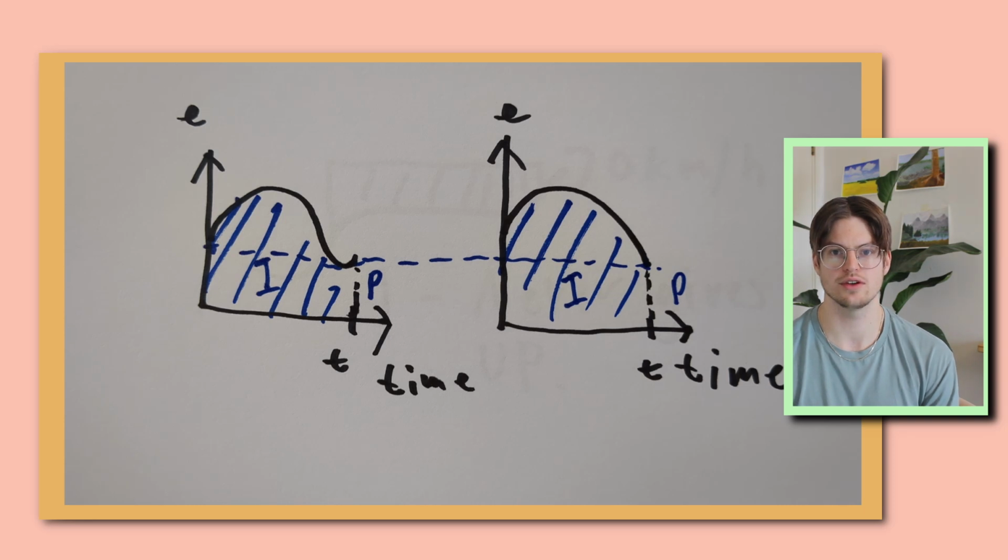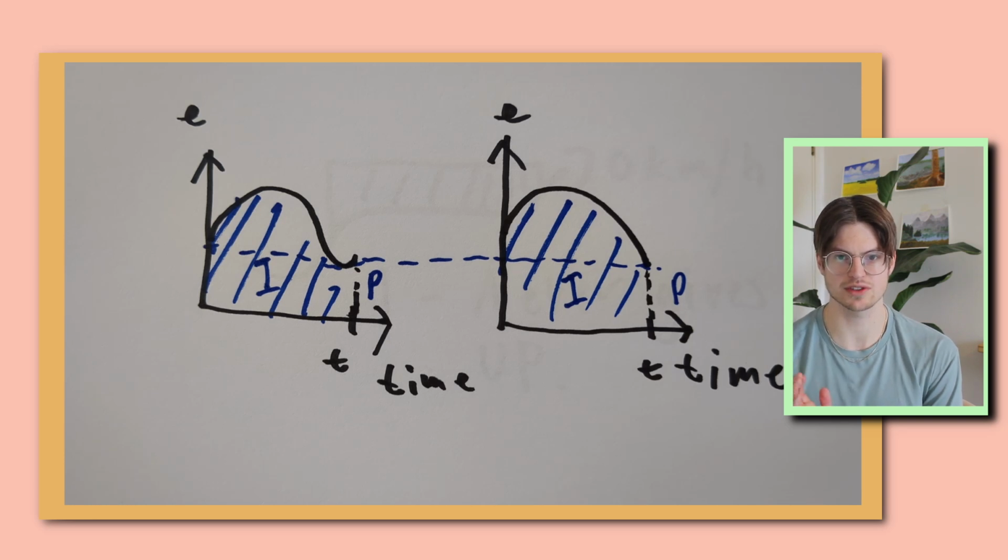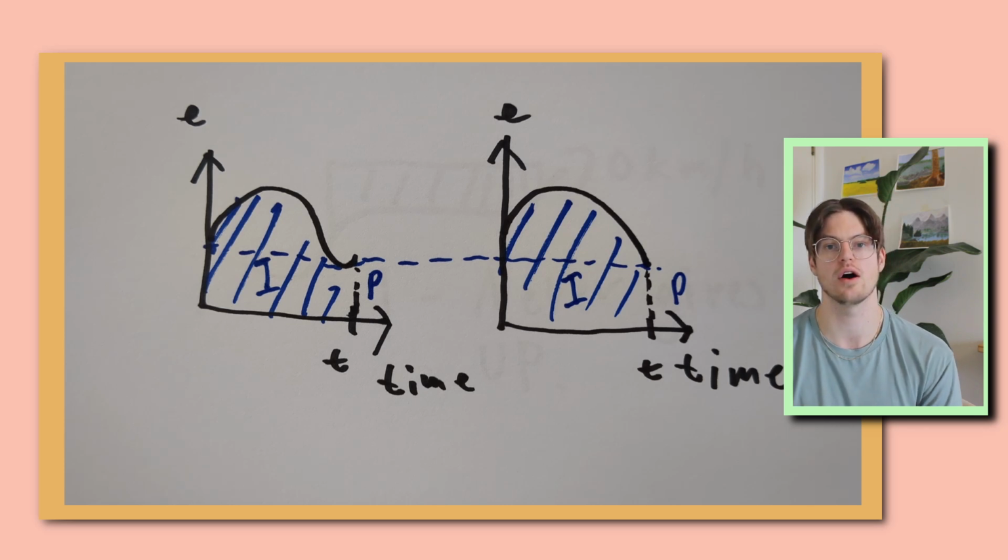At some point, you will know that you can turn off the stove and it will still continue heating. You know that the temperature is heading up, and then predictively you can turn down the control signal. You're predicting the future. You're predicting that it will continue going up so I can ease off of the control action.